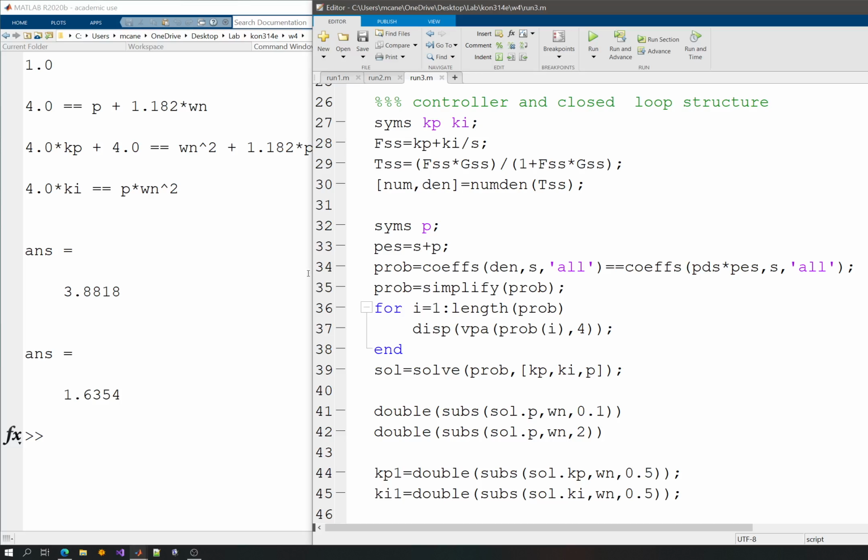If we have a zero in the dominant region, it is very bad. It's even worse than having a pole at the dominant pole region. It was having a 300% overshoot value, whereas the pole was just 100% overshoot. So keep that in mind.